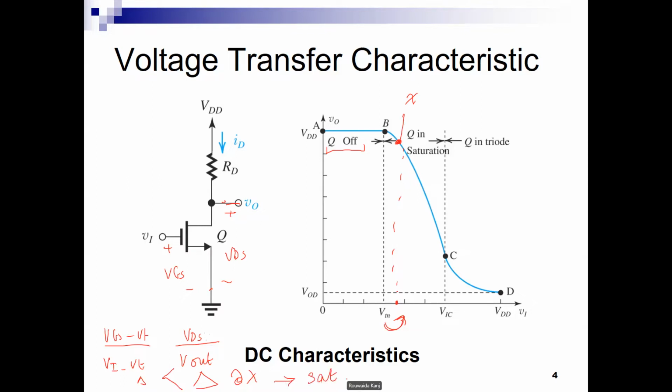saturation. So it is very important, when we try to figure out the region, that we relate VGS minus VT for the transistor in terms of Vin and Vout, and then find which quantity is larger in the specific region. So we start off, set, and when the device pulls down the output strongly, this becomes small and the input is large, we are in the linear region.